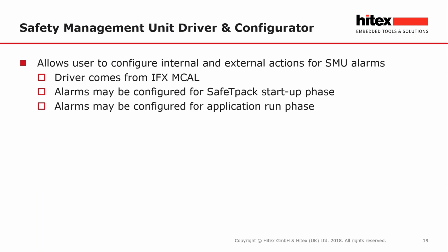So the safety management unit configurator and driver is the final part, and this allows you to configure the SMU for the SafeTpack startup phase, so it's able to then handle all the alarms coming back from the individual tests, for example, the LBIST. But once the SafeTpack startup phase is ended, you can then have a configuration which is the one that your application will use during the actual run phase.